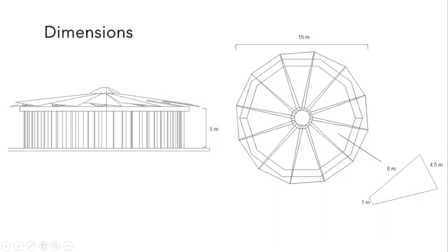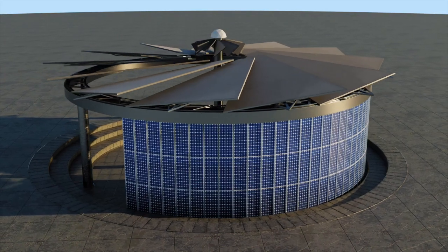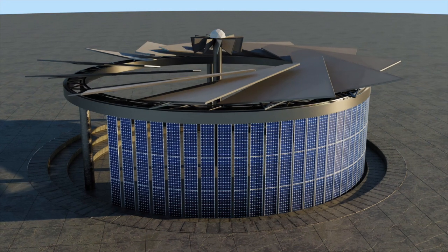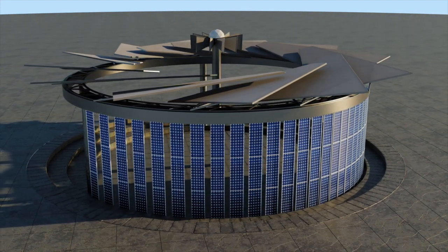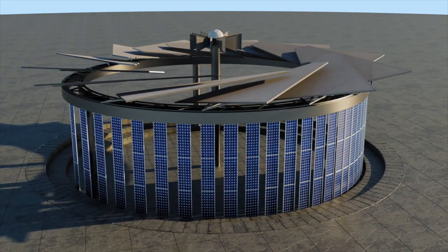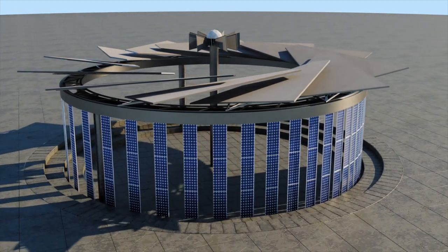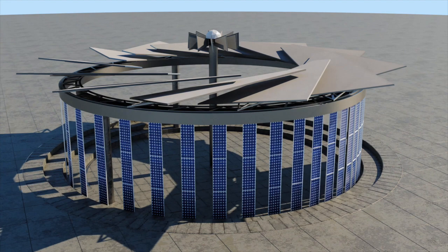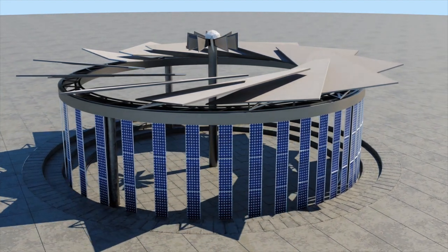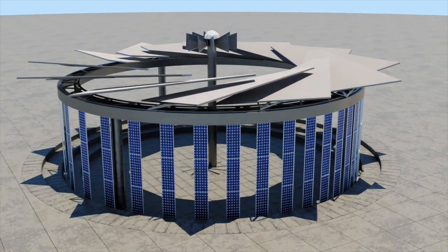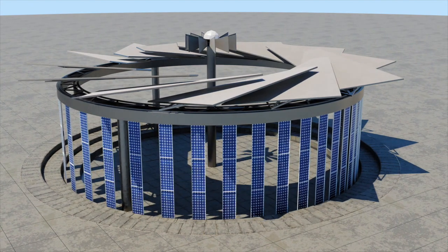The pavilion consists of a cylindrical steel structure with a 5-meter height and 15-meter diameter circular roof that has 12 polytetrafluoroethylene fabric panels. They move to form an aperture to provide shading when it's necessary. The base of the pavilion consists of 27 integrated PV panels that slide in a track in correspondence to the sun's position and wind direction to generate electricity, provide ventilation, and block undesired wind.